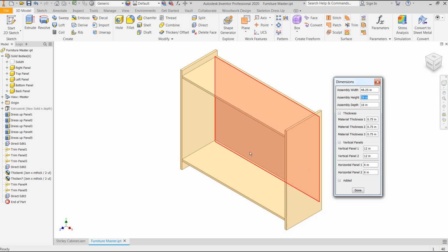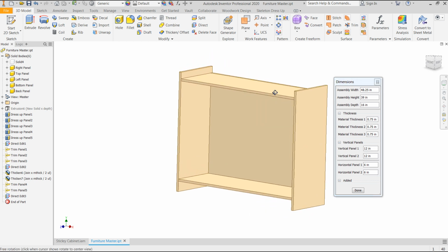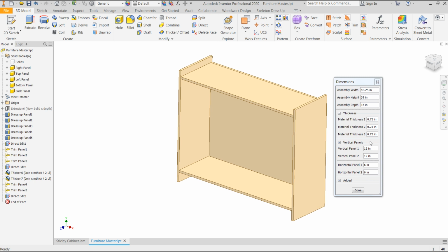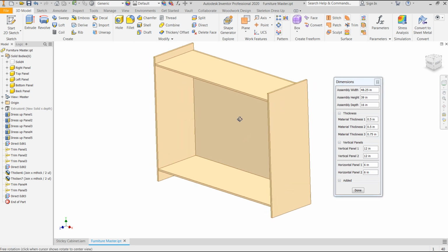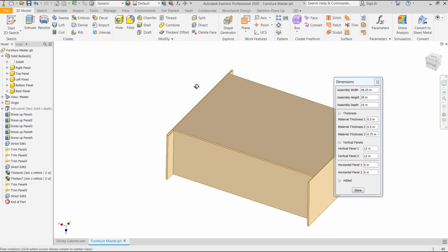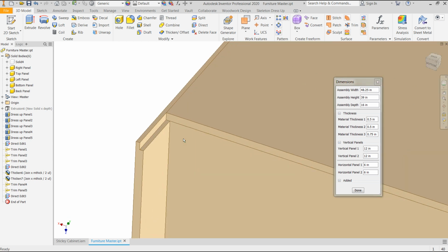Now let's go further with this. If I wanted things to change in thickness, let's say it should have been 1 inch, I just adjusted everything to 1 inch. If I say it's a 1/2 inch, 0.5, it's now a 1/2 inch. What's interesting about what I'm doing here is take a look at the data. It's always going to be halfway into the part.